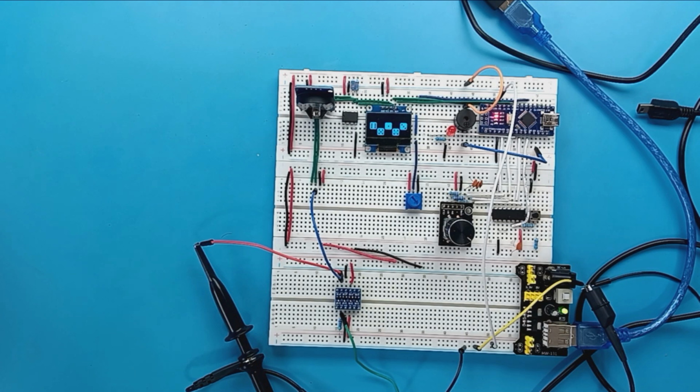When using a prototype board, one of the key issues is it's not great. There's a lot of metal inside it, and that can create stray capacitance. And that stray capacitance can do lots of unwanted things, like rounding off edges of signals. But I'm not too concerned. It works fine. So let's try the next thing.